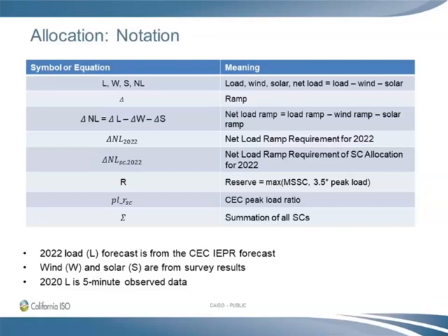After all the study, calculations, and analysis, we will have an estimate of how much net load requirement we are going to have. As well, from that study, we will have how much the load ramp will be in the maximum 3-hour ramp, and in the max 3 hours of net load, how much is contributed by the wind and by the solar.